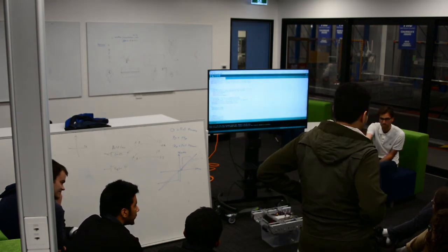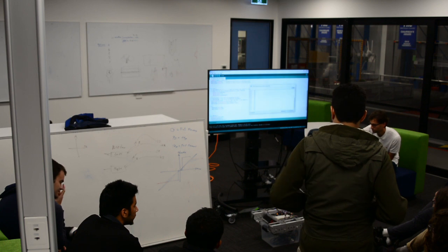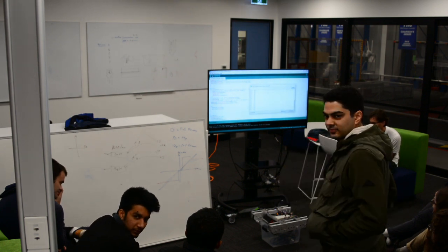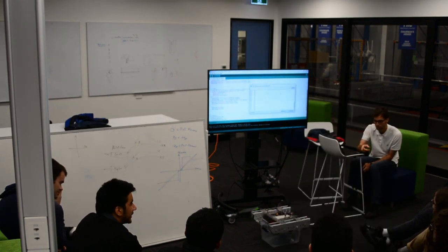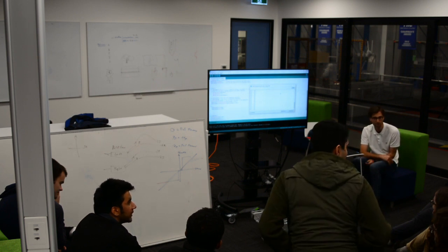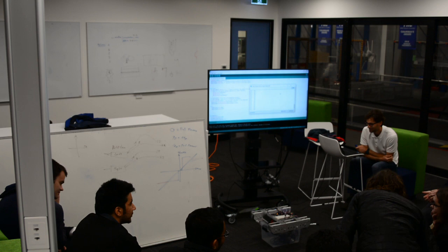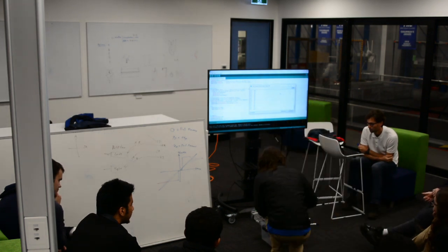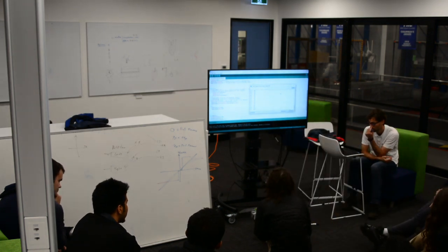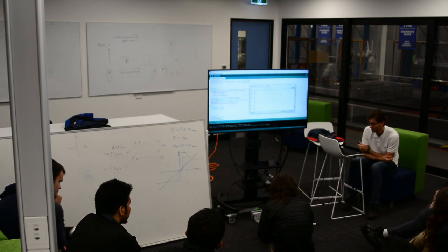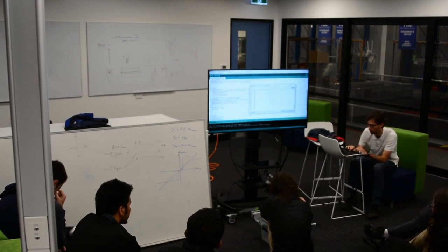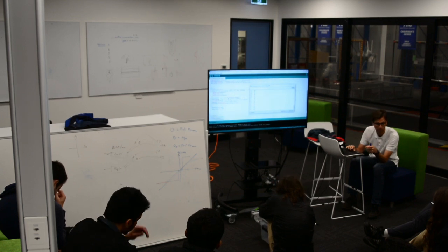So it looks like we're getting pretty close, but the left one's just overshot a little bit, right? Okay, so we could potentially put it on the ground and then reconnect the serial port, and it should still be putting out the correct data. So let's just increase this to 1.3, and then we'll run it once off the ground, and then we'll run it on the ground and see if it's any different.